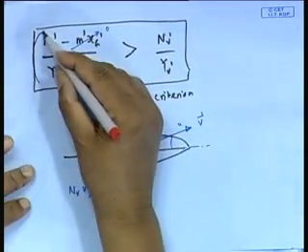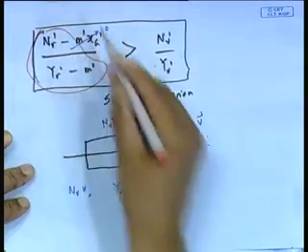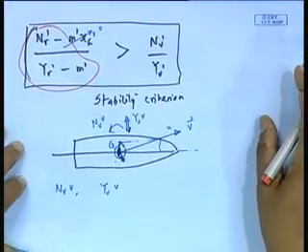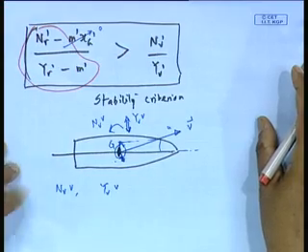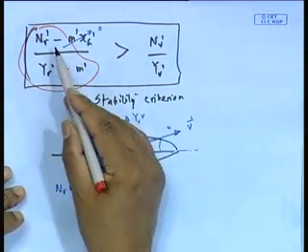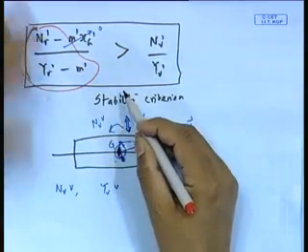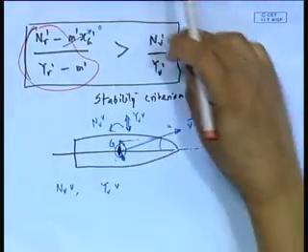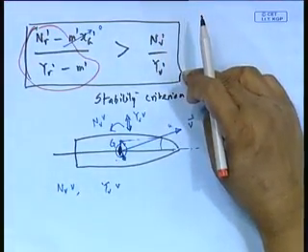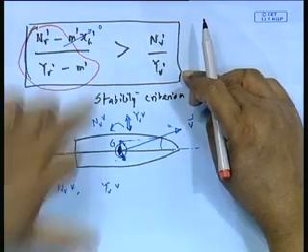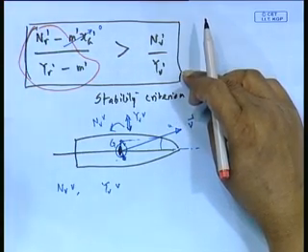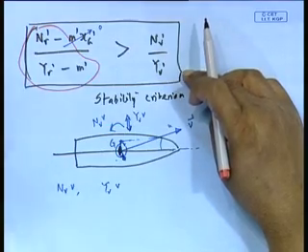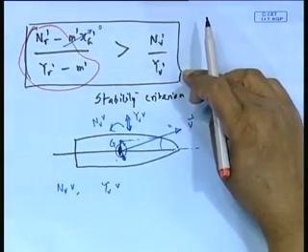if you look at this term in a similar way, this full term becomes the center of pressure, so called, for pure yaw. See, this comes only for yaw motion, Nr by Yr for yaw motion. So this term represents the distance from the center of gravity of the point of action of force if the ship was having a pure sway, just v.